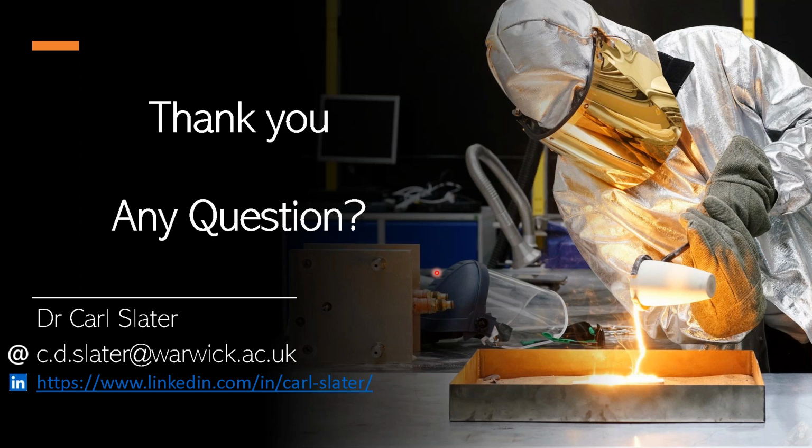I will typically use 2 layers of graphite foil, then a tantalum foil on the bottom, because heat rises and you need to get a little bit extra resistance in the bottom one. But it's a delicate balance, really. It really depends on how good your atmosphere is, how worn your anvils are.